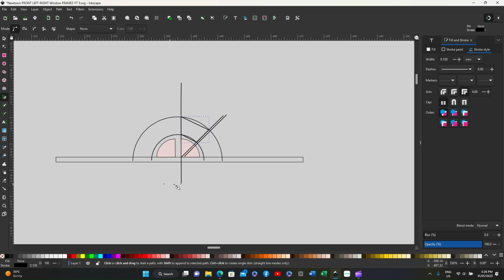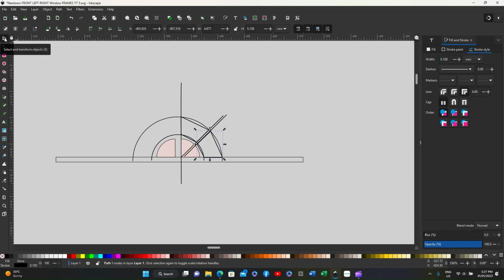Click on Select Draw a Line again, and this time start at this particular point here to here. The snapping tool will assist you. And again, change the thickness of the line to 0.1. Now it is a bit fiddly, but it does work with the snapping tool on.